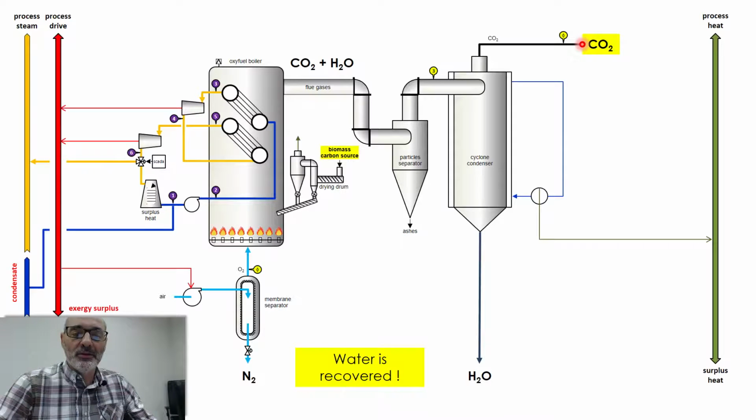So you get some amount of CO2, which is cold here, typically, I don't know, 60 degrees. You inject CO2 here, and this recycled CO2 plays the role of N2 in a traditional boiler. I'm going to show you that with biomass you don't have to do that because it already has humidity.